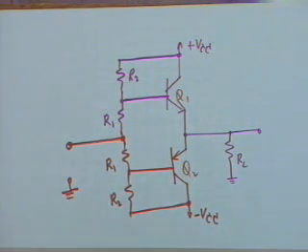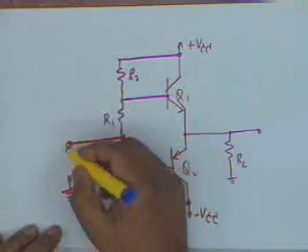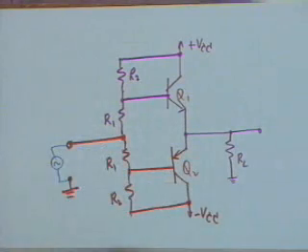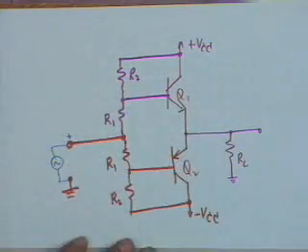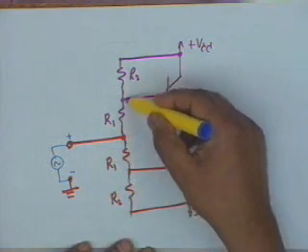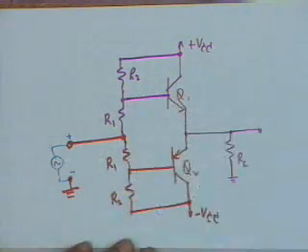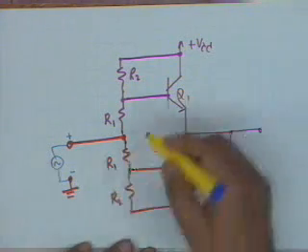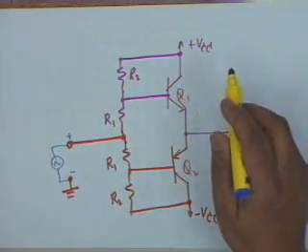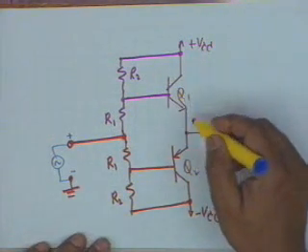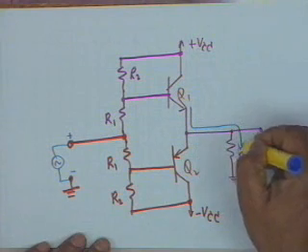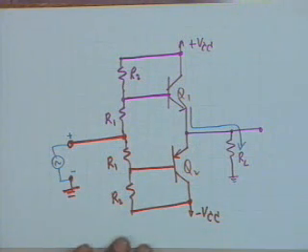Let us see what happens when you connect an AC source, let's say here. When you connect a signal source here, when this terminal is positive with respect to this terminal, then current flows like this. The NPN transistor conducts, and it allows a current to flow like this. Is that clear? Why doesn't the current flow in this direction? Because Q2 does not conduct. Is the point clear?